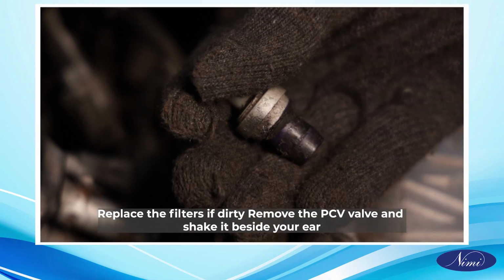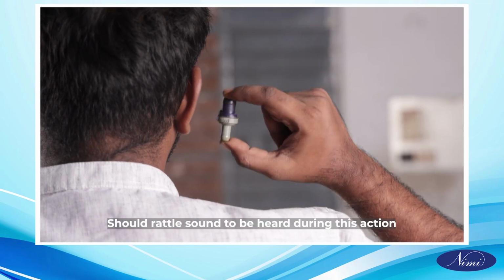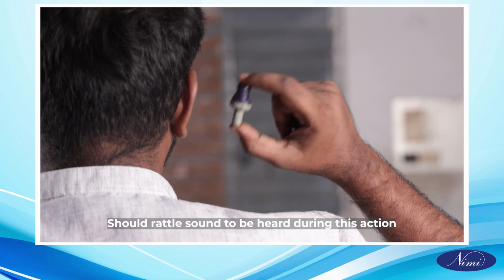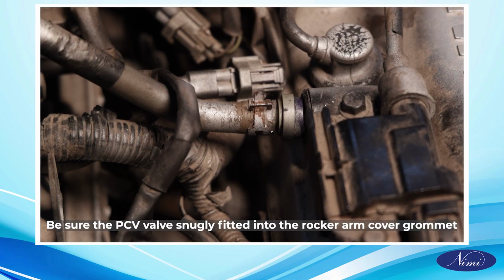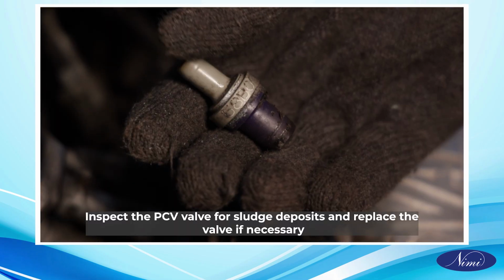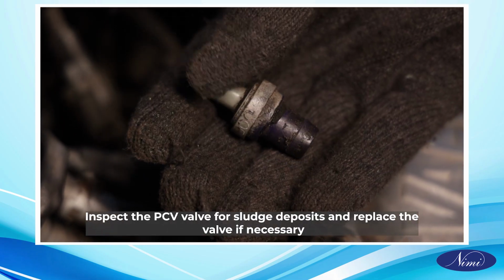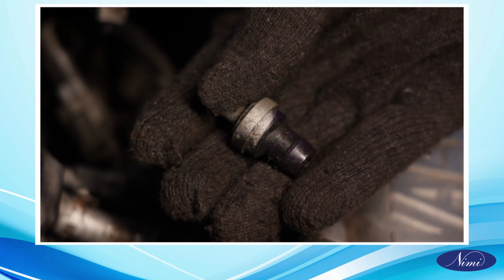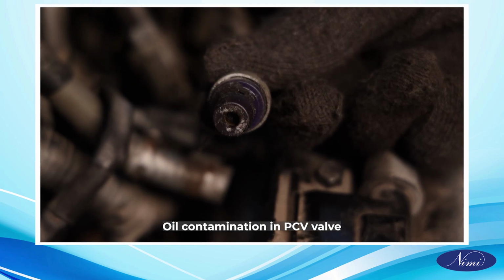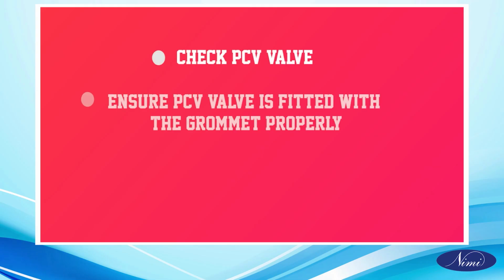Remove the PCV valve and shake it beside your ear. If a rattle sound is heard, be sure the PCV valve is snugly fitted into the rocker arm cover grommet. Inspect the PCV valve for sludge deposits and replace the valve if necessary. Oil contamination in the PCV valve. Check the PCV valve. Ensure the PCV valve is fitted with a grommet properly. Damaged PCV hose.